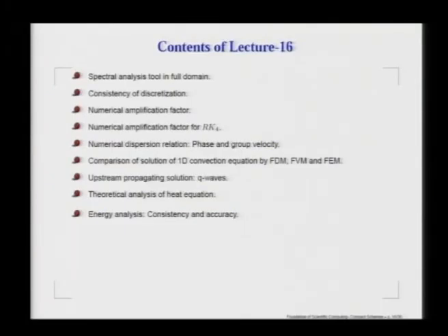Today's discussion, lecture 16, begins once again with our discussion on spectral analysis tool. As we mentioned before, we would like to develop an analysis tool which is applicable for the full domain that would have different types of discretization for different points. In this context, we have already discussed in the last lecture about equivalent wave number. Once we have developed equivalent wave number, we are going to talk about consistency of discretization in terms of this equivalent wave number expression.